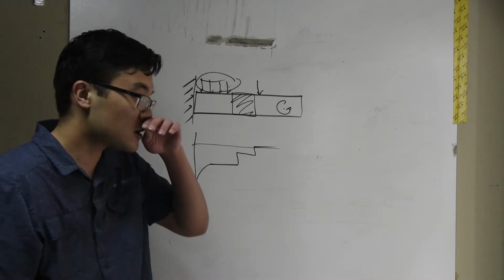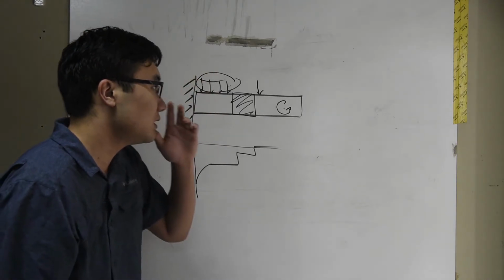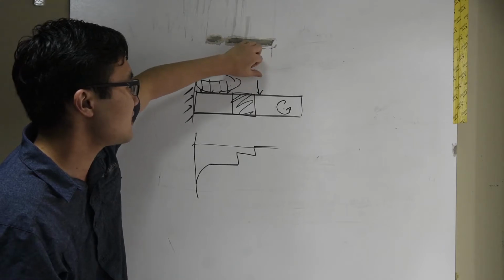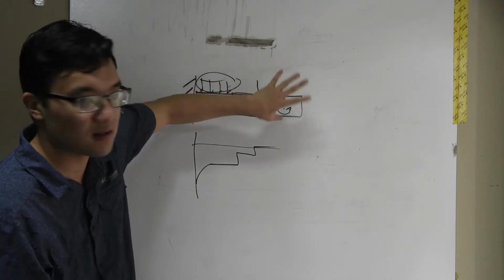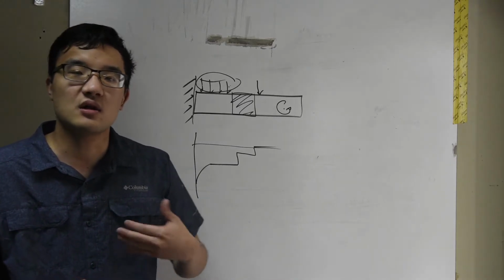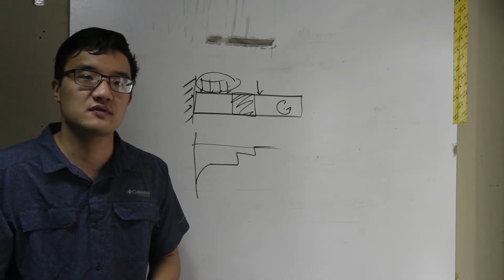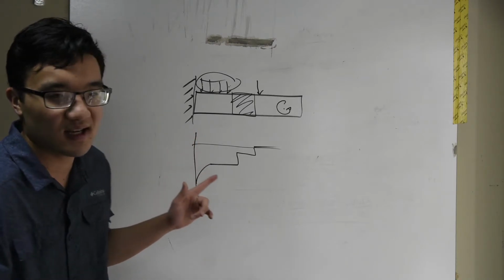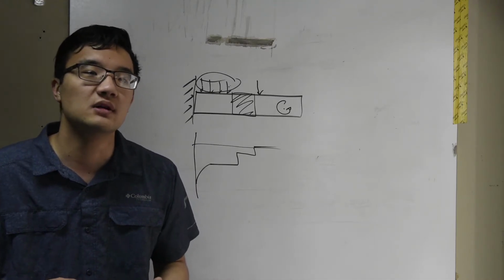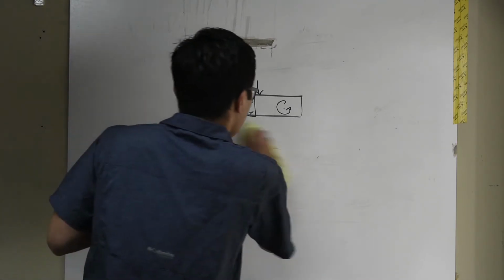As long as you keep track of your directions, just take a discontinuous function, define your moment equation, moment balance for this section, then do it constant here, then define it at this point, and then define it at that point. You're good to go. It's not any additional level of complication as long as you understand how to break this down by taking that cut and exposing those internal forces. And we've talked about that a lot. I'm confident you guys can do this. So if you understand the key concepts in the centroid analysis that I've talked about, this is not any more difficult.